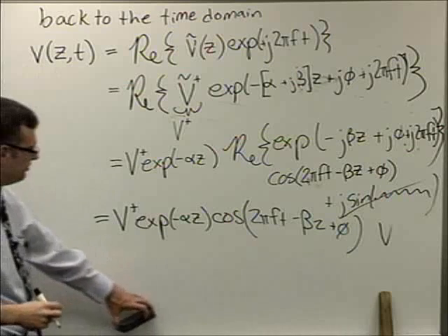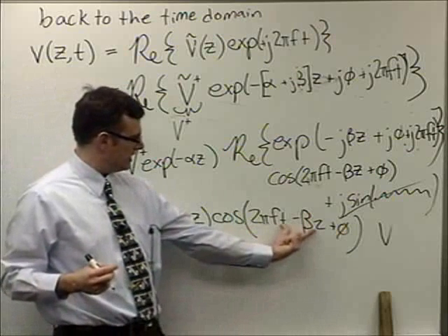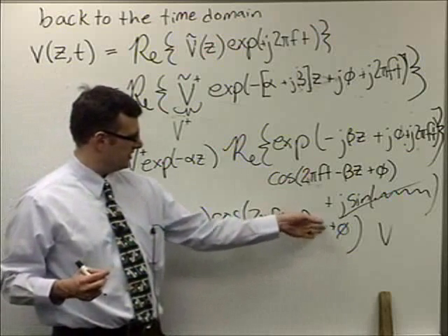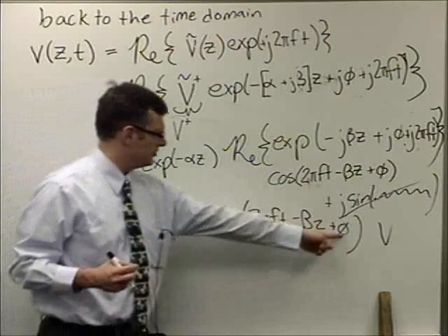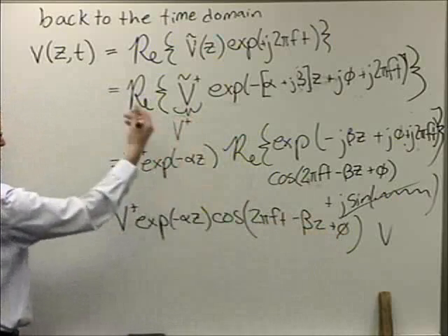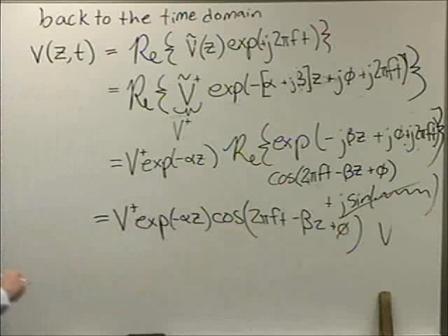And you see we got that nice, beautiful traveling wave expression here. Frequency times time minus wave number times distance traveled, and an arbitrary phase value. At any point, if you set z equal to a constant, you get an oscillating sinusoid and exponential attenuation of the amplitude depending on how far along z is. It's a good exercise to work through, being able to convert a space-varying phasor back into a time-varying quantity, just to clarify the complexity. This solution is a little bit more complex than those constant amplitude waves that go back and forth on the transmission line.